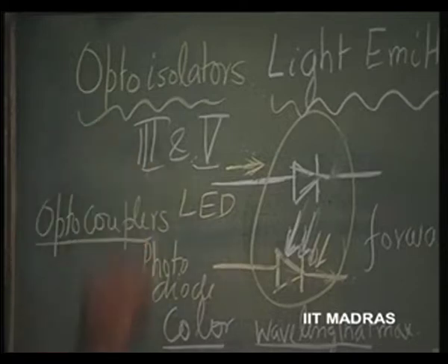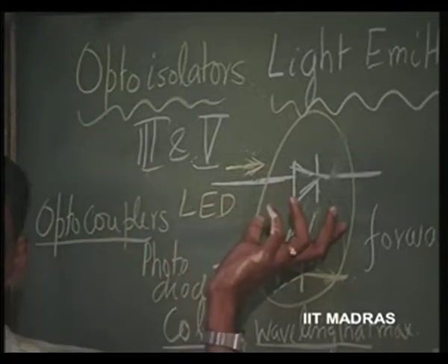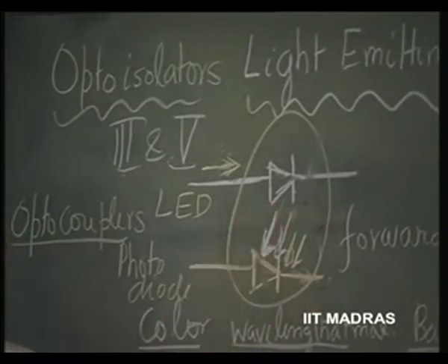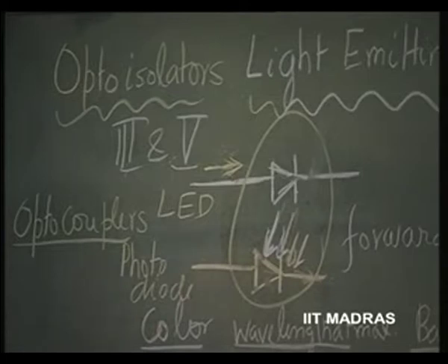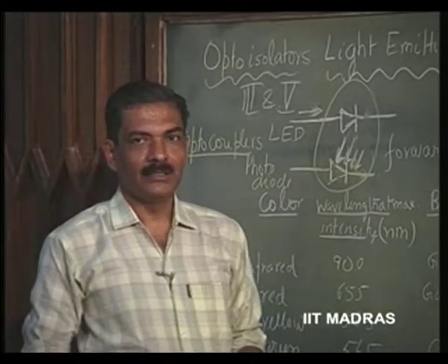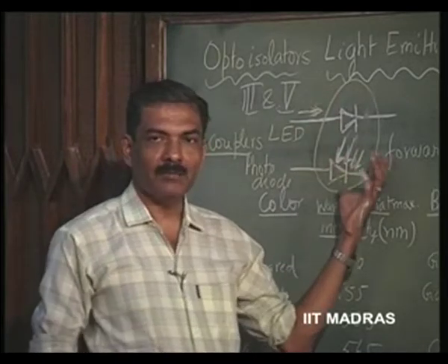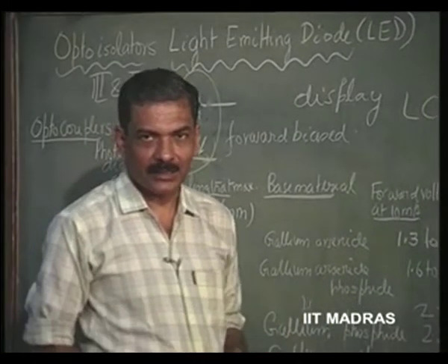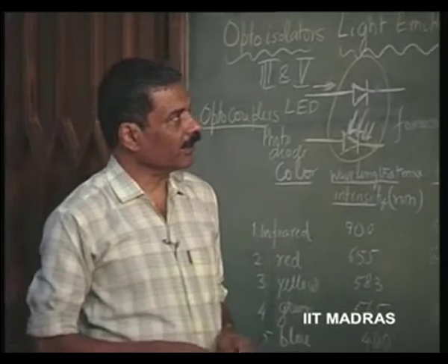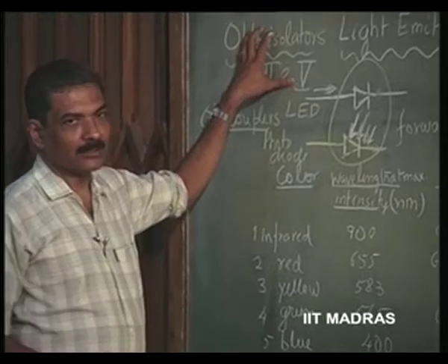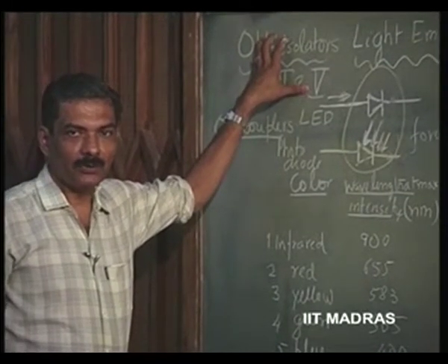or opto isolators. Important units like this are available for a variety of applications, where you would now rather not use transformers and things like that for isolation purposes. You would like to use some electronic element like this, which is quite convenient. Very intelligent designs are available where this can be used for precision measurement of current in high voltage circuits, etc. So, this is another application of this combination of photodiode with light emitting diode, which is called optocoupler or opto isolator.